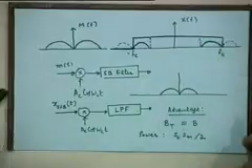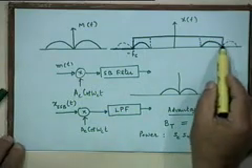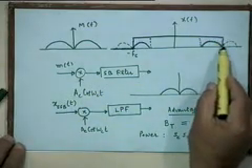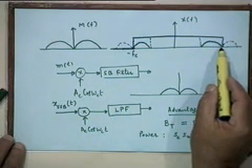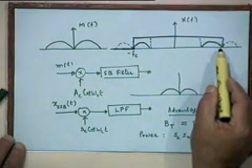For an ideal tuned filter, the Q is infinity, but as Q becomes finite, as it becomes smaller and smaller, the bandwidth increases, right? So you require a Q of a suitable value, and typically because you require very sharp cutoff, you require very high Q filters.